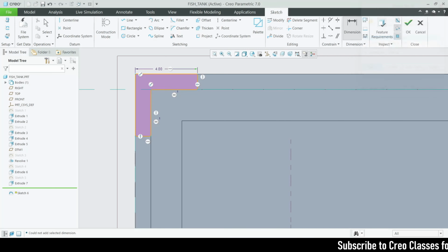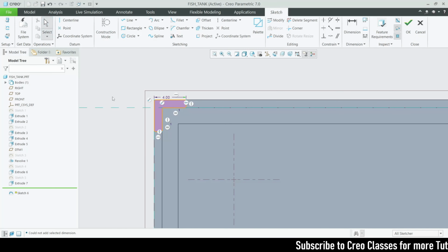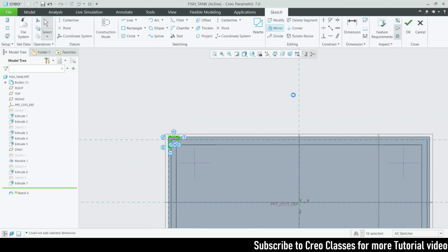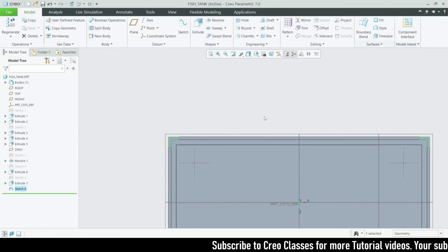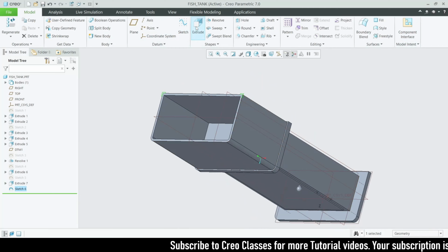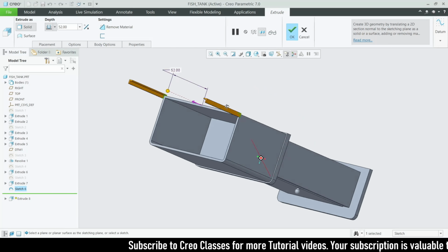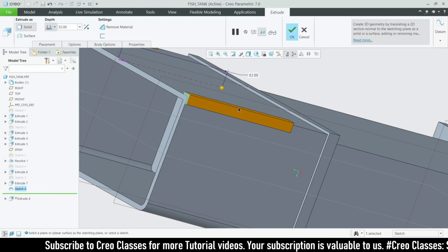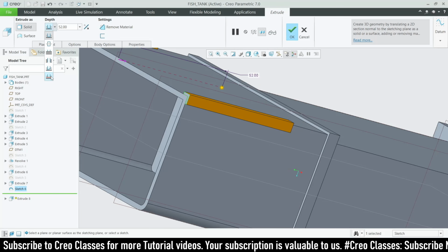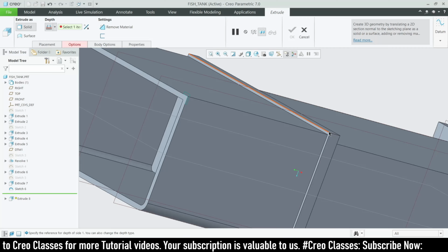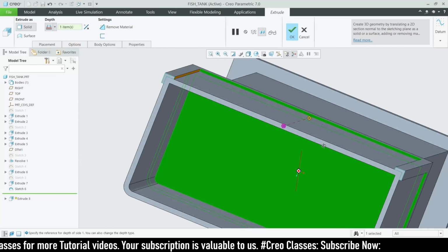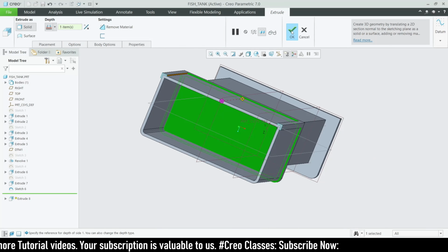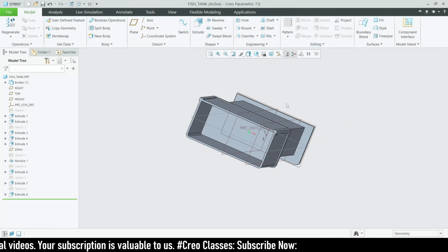Okay, good. So let's select all this, and I'm just going to mirror this towards this center plane on the opposite side. Let's click on OK here, and then I just want to extrude this, flip the direction, and select it to this space. Okay, it looks good, right? It looks like a frame here for supporting that mirror.